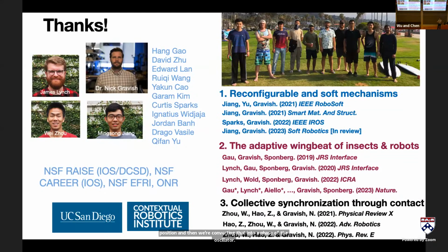If you have your servo motor driving this flexible column, and now through contact, that column, instead of translating into some reduction in speed of the motor, just buckles, I think a lot of things are going to be different in terms of how well this synchronization process is going to happen. All of the analysis is predicated on contact inducing some kind of phase delay of the evolution of the undulatory gait. That might not be true when you have soft elements, where the compliance of the body can accommodate the generation of displacements at the joint that then don't track all the way out.